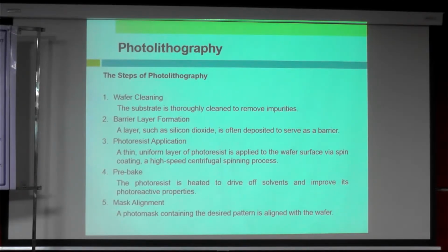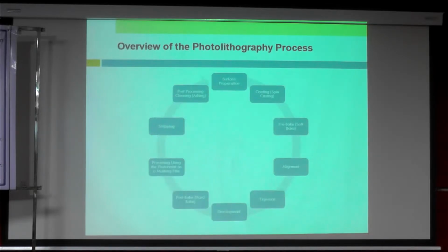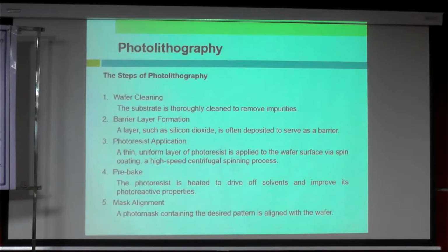So the steps are roughly mentioned here, but now we go into the detail of the process, where firstly we normally use a wafer, a silicon wafer. Then we do the cleaning. The substrate is thoroughly cleaned to remove impurities. Impurities can be oil, dust, etc. We have a special process later on where we introduce this.